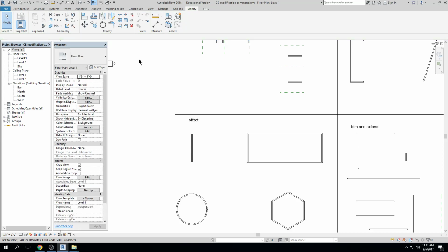This one is very similar to AutoCAD. So offset, click. It's going to ask me to input the offset distance, okay? So 1 foot. I could also type in something like 5 foot, enter, okay? You'll notice there's a copy option here. So right now, if I offset my first object, it will copy it. So it will leave the original object and copy a second object. If I unselect that, it will move that object. So it will delete the first object and just keep the copy, okay?